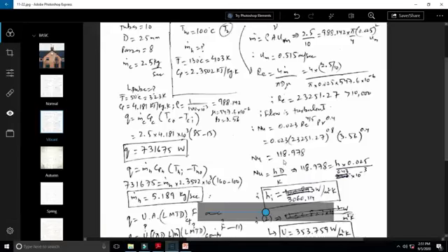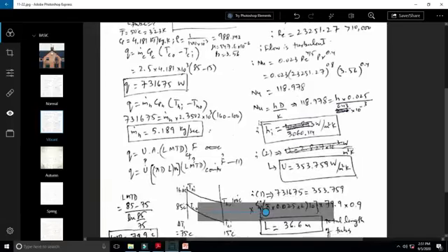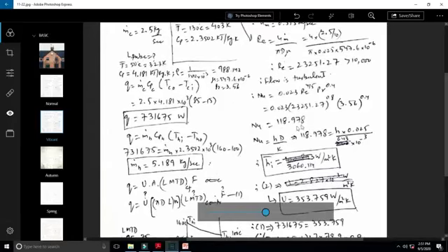So at the end we will be able to calculate the Nusselt number as 118.978, and then as usual we will equate this Nusselt number to HL over K, or rather HD over K, because it is the pipe and not a flat surface. So Nusselt number is 118.978. The value of H is HI, which is the unknown.